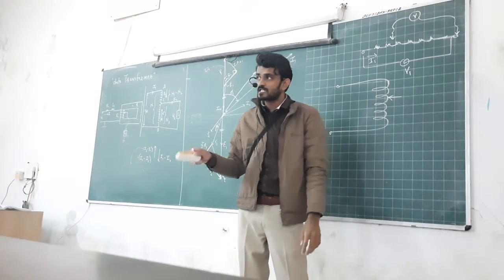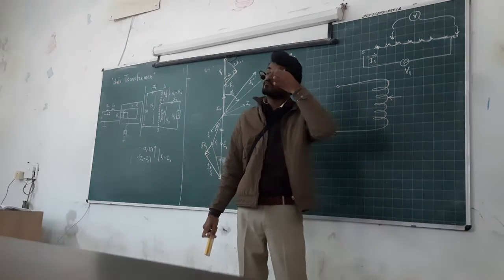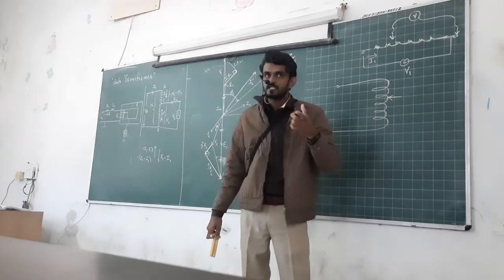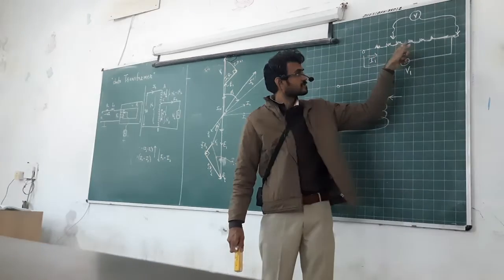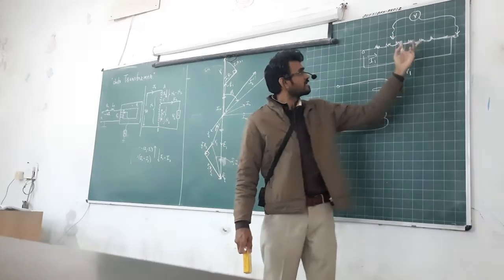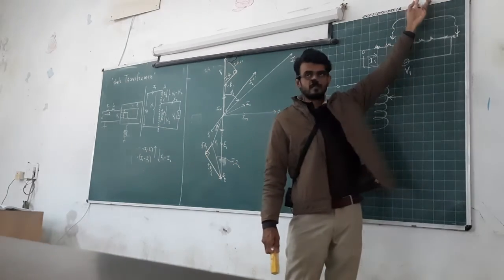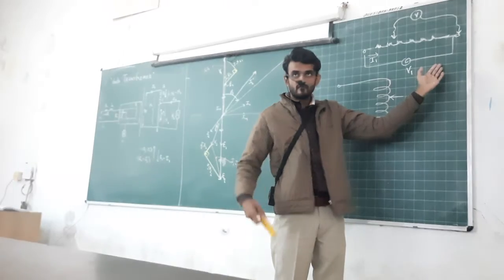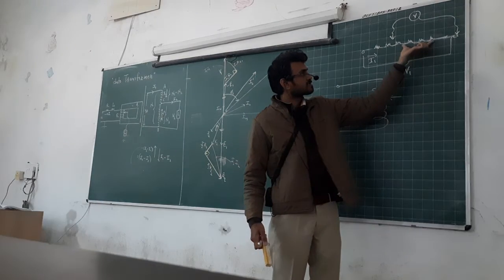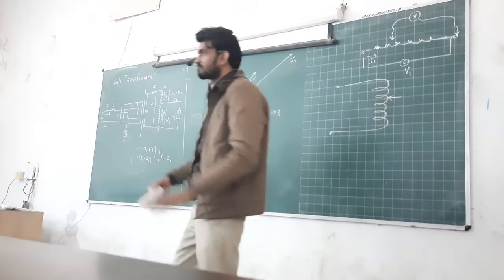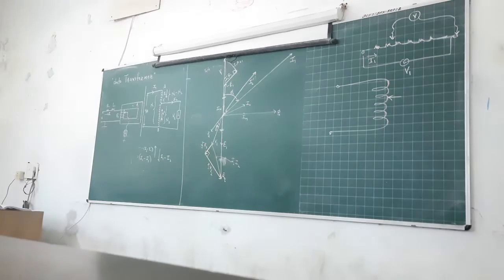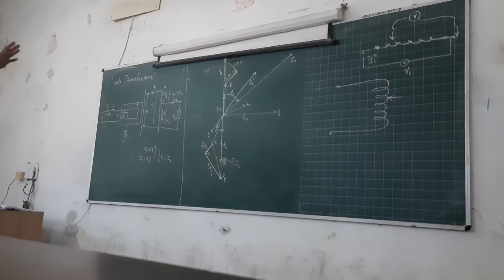And in electronic circuits that will happen. In some electronic circuit 3 volt is needed and we have 5 volt, then they will put some resistor, and after that resistor they will take a tapping. From the tapping they will give another voltage to the other circuit. So here is the 5 volt, I want 3 volt, then I will connect across only this portion of the resistor and apply that voltage to the further circuit. So that will divide the voltage by the resistor. It is called a voltage divider, and there is a rule also, the voltage divider rule. In the same way, when parallel resistances are there, there will be the current divider rule.